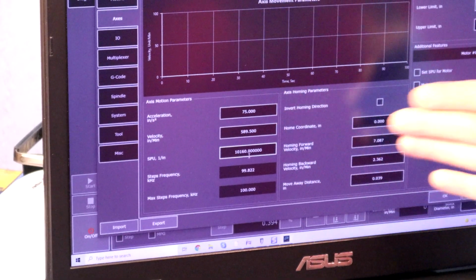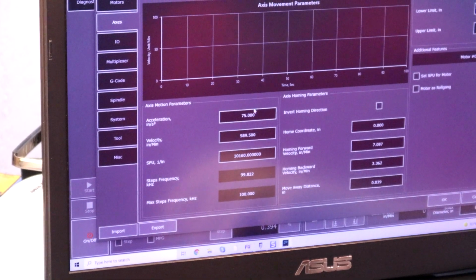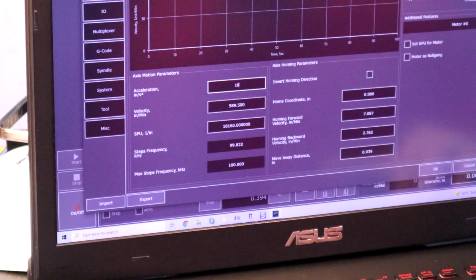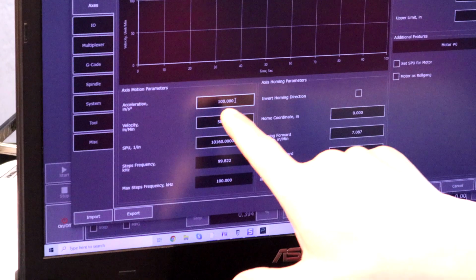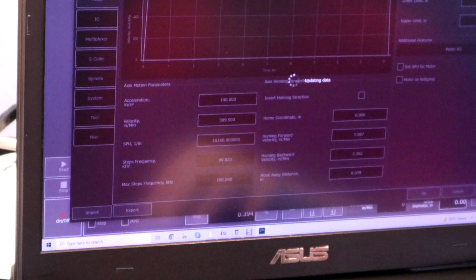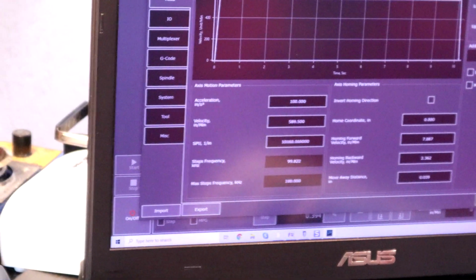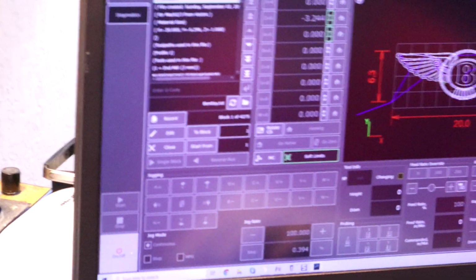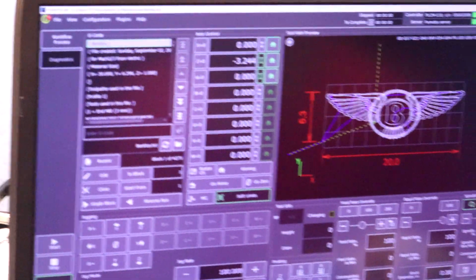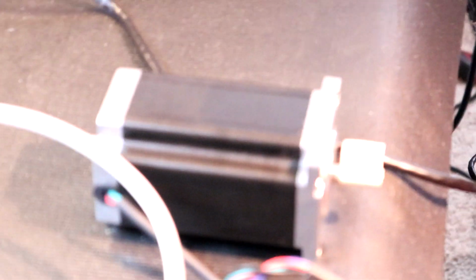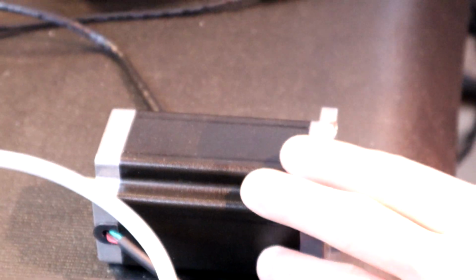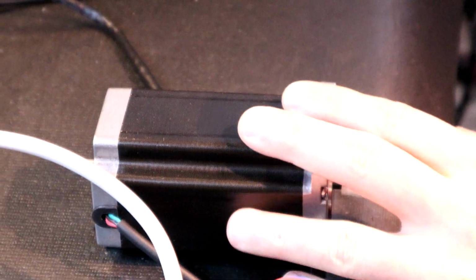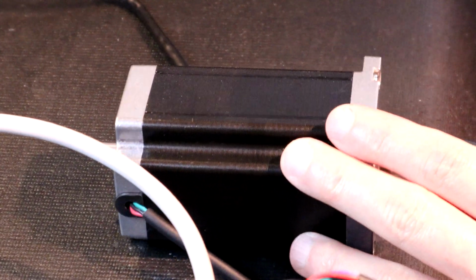And you can see exactly what we're talking about here in the number factor. If I go up to 100 on acceleration, now we've just increased our acceleration that much faster to go to that 589 inches a minute. Watch this. You'll see that differential in G-force become prevalent very quickly. Turn on the actual system. You ready? Watch the motor. Look at how fast. Look at that torque. There you go. That's what 600 ounces, 37.5 inch-pounds of torque will do instantaneously.